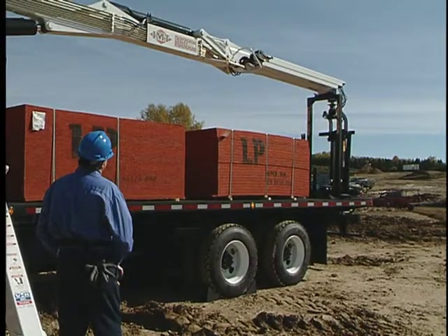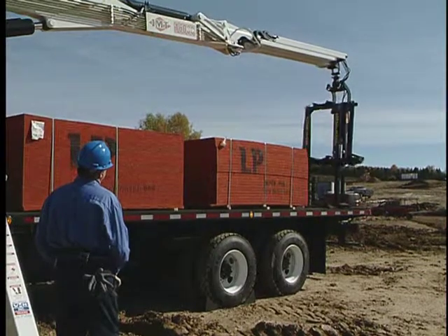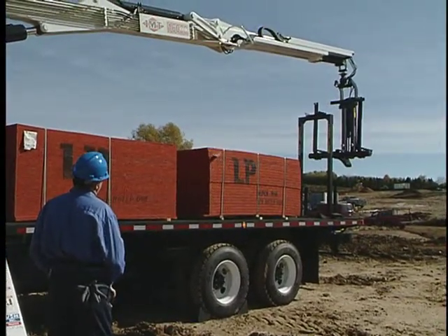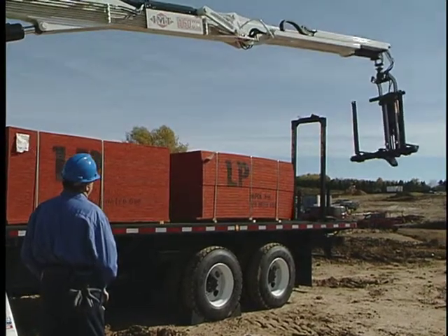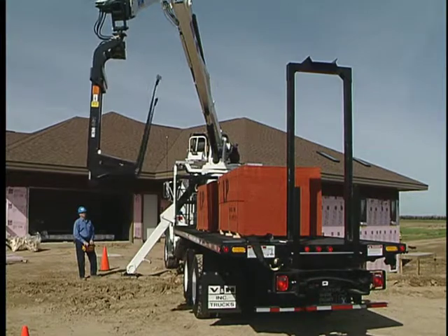For the first lift, the fork must be safely lifted out of its cradle, clearing the cradle structure. Run the extension out to clear the end of the truck and rotate boom to clear boom rest. This is the typical operation for the first load.